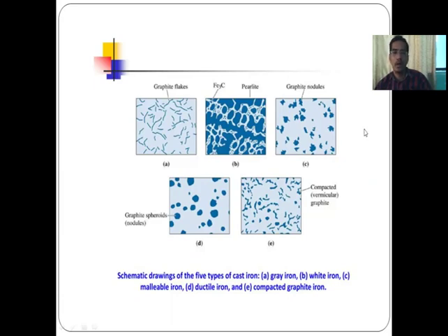And if high strength or damping products are required, then we will go with cast iron, like a lathe bed. Then different valves for safety, pressure relief valves, pumps, pump casings, or different agriculture equipment are manufactured using cast iron material. So this is all about steel and cast iron.